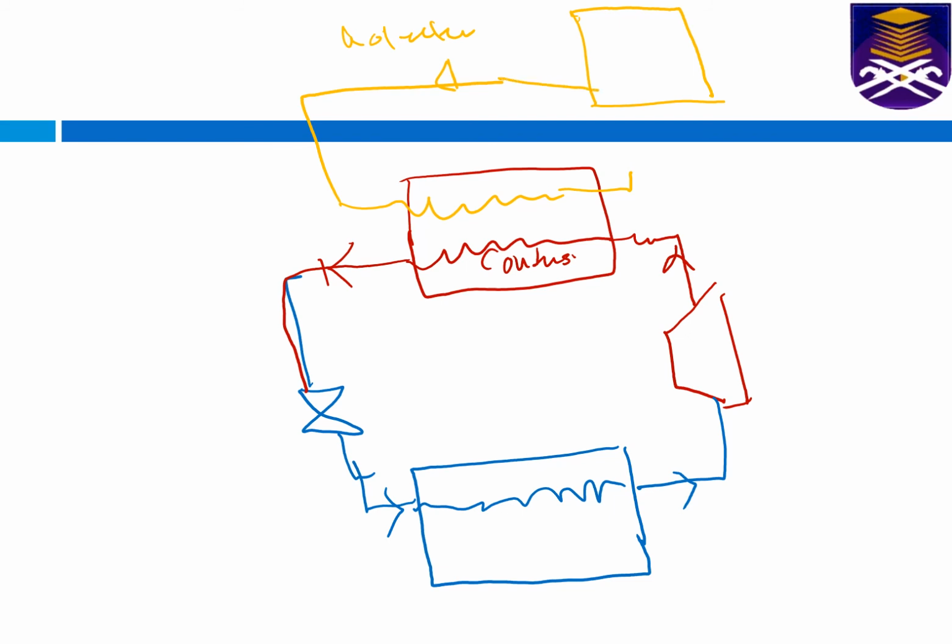Okay, cool water from the wet cooling tower. Then this is your fin before, so before that, coming in, and then after that this is going to be wrapped here, because this is hot water, and then it's going to be sprayed here, and then here you have a fan.